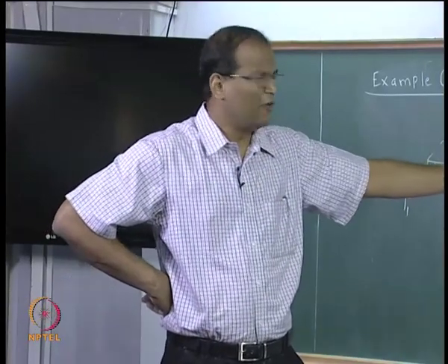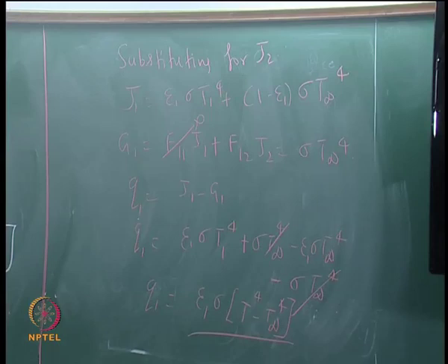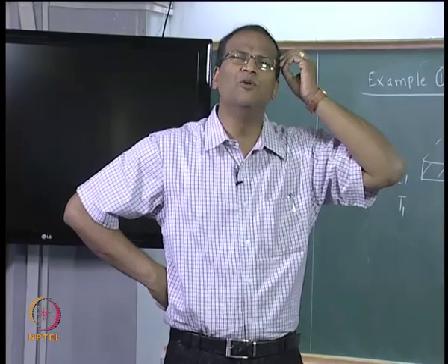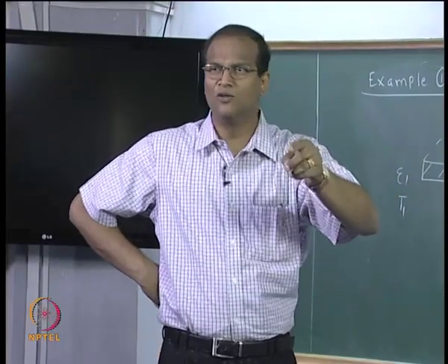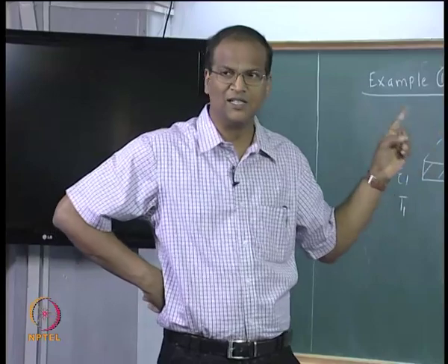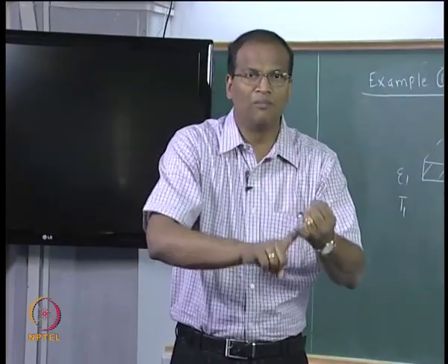This is a formula which you learn probably in high school, or maybe you learnt it again in the third year heat transfer course. This is one of the most used, and one of the most abused formulae in heat transfer. Now having gone through this course, you must know what are the limiting conditions under which this is valid. Single plate at a uniform temperature.